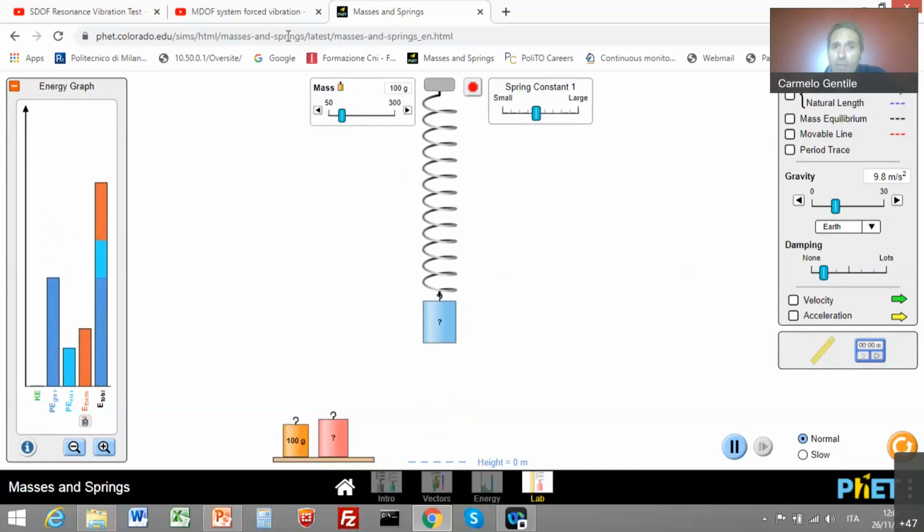So now we have effectively understood the effect of the structure on the response to an applied motion. The stiffness and the mass are very important because the combination of mass and stiffness of the structure determines the fundamental period or the resonant frequency of the structure.